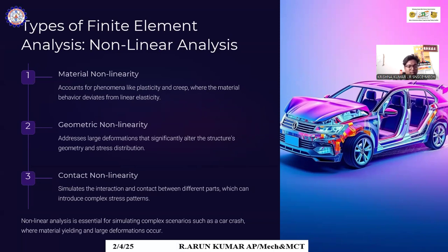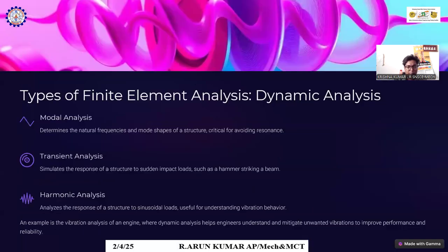Contact non-linearity simulates the interactions between parts, which can introduce complex stress patterns. Non-linear analysis is essential for simulating complex scenarios such as a car crash, where the material yields with large deformation.